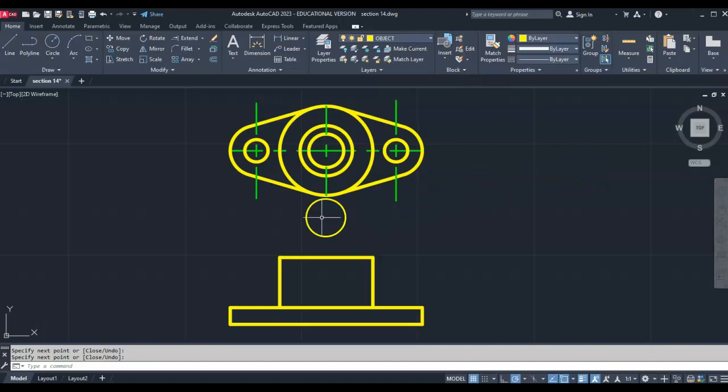alright, for all of this internal stuff, these are holes. This hole goes the whole way through, this goes the whole way through. This hole goes down a certain distance, and then the smaller one goes the rest of the way through. So if this was a normal, regular multi-view, all that stuff is going to be hidden.